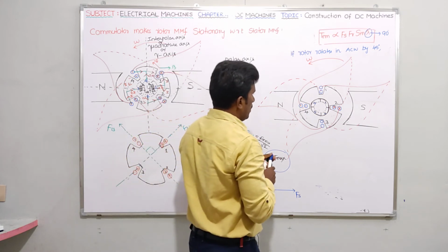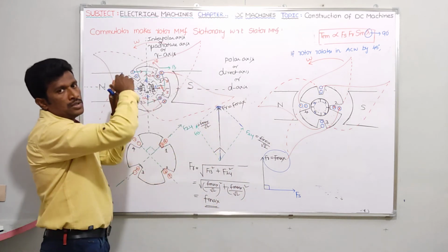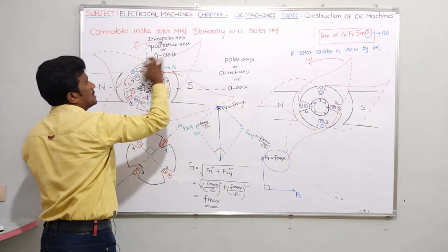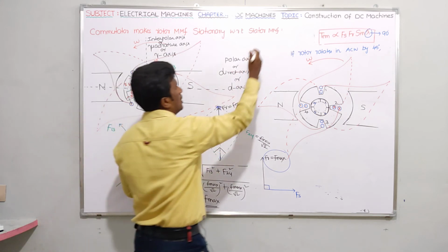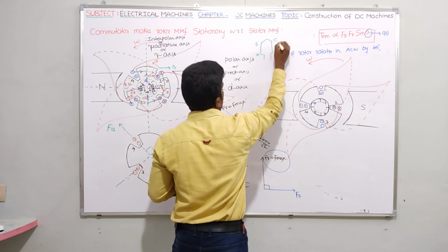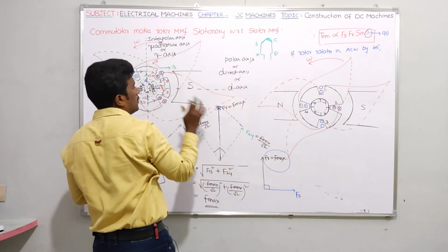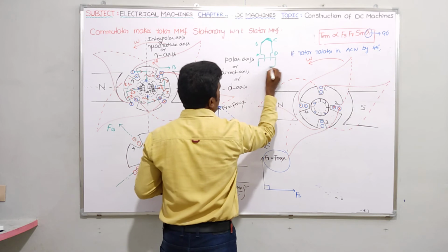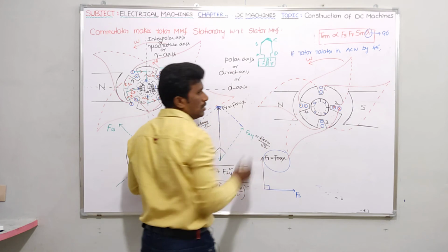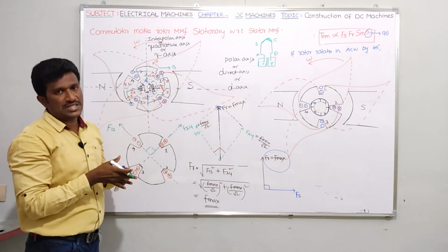Right. Now guys, observe. Please try to see here. Yeah, and one more thing I told. So I told you, if you take a coil, overhang portion is nothing but this portion. Overhang means this portion, whatever you are able to see, this red color, this is the overhang portion. Don't confuse. Overhang means this one. If you take A, B, C, D conductor, then BC is the overhang portion. This only you are able to see in this red color. Okay, and the other end I told you it will be in connection with the commutator segments, right? Yes or no? So let me connect coils to commutator segments now.